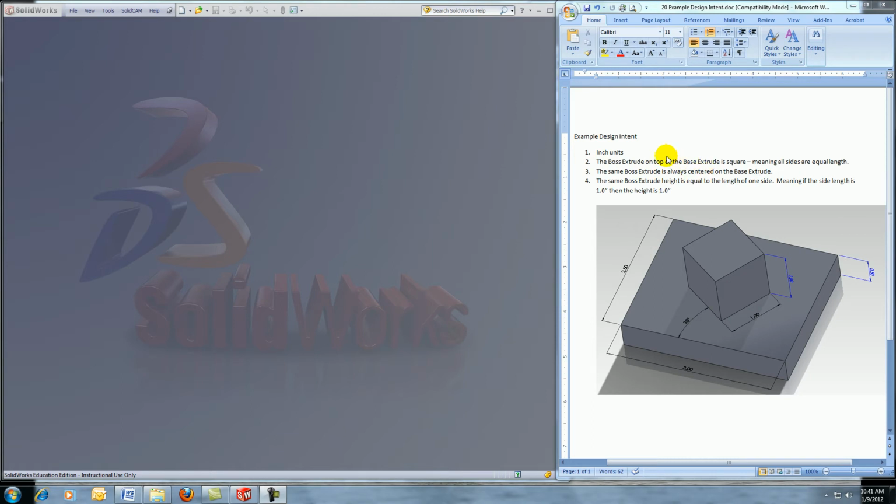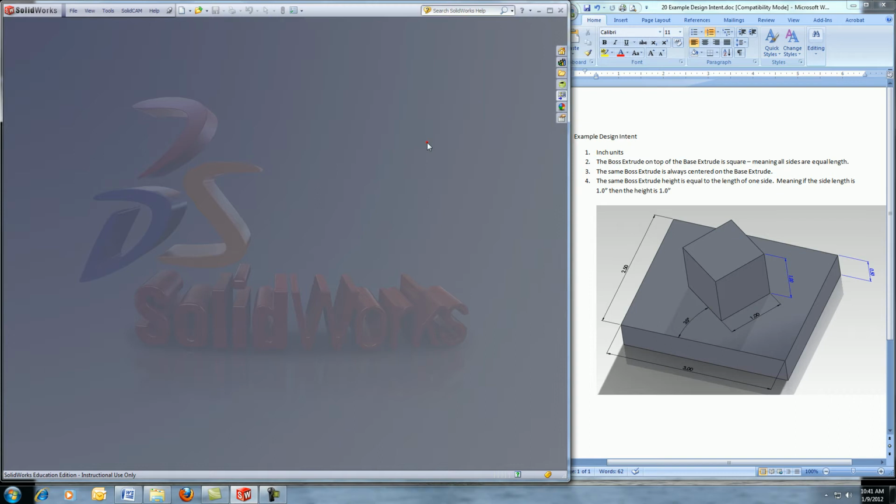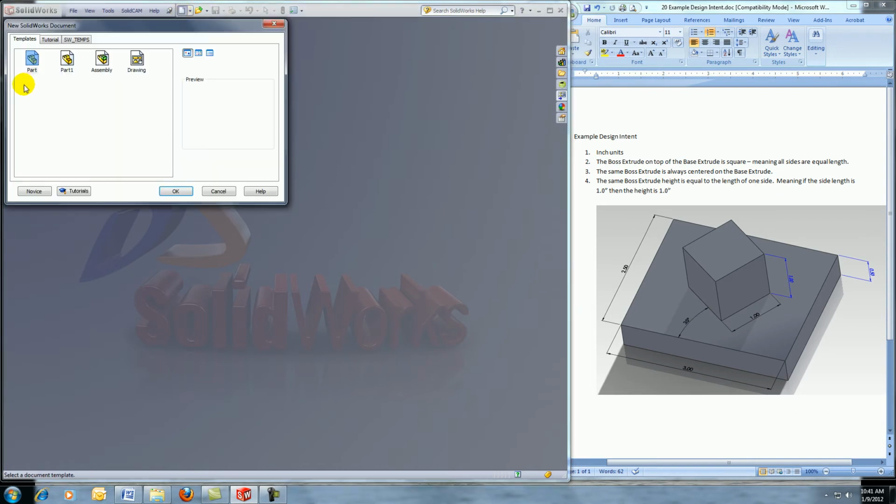And as I mentioned before, look at the drawing or drawings of the part or what you're trying to accomplish. Pick up on the subtleties of where origins are and extrusions and things like that. So if I look at this part, for example, I can see the dimensions pull from this corner. So this is the corner that I will use to make my 0, 0 origin. So over in the SOLIDWORKS direction file, it tells me I'm in inch units, so I'll start a new part.